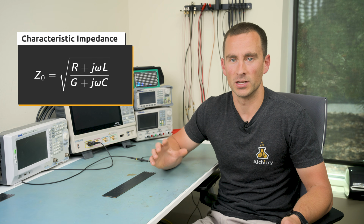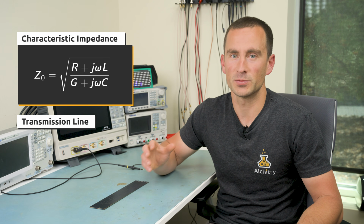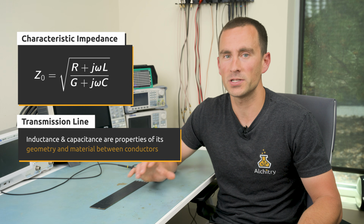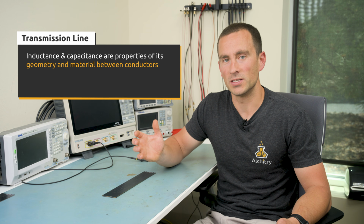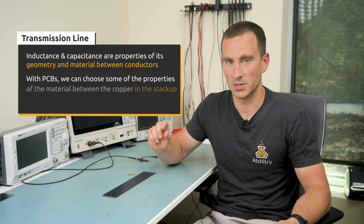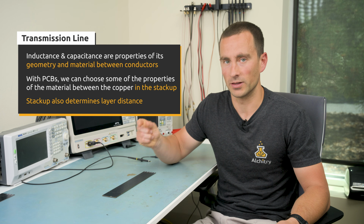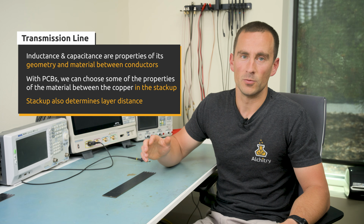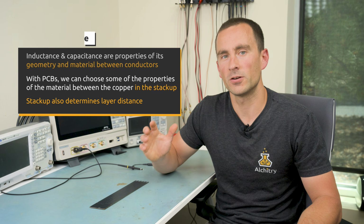The major difference is that the energy in the cable travels down it, but the energy in a resistor dissipates as heat. Looking back at the equation, we can see that the impedance of a wire is mostly determined by its ratio of inductance to its capacitance. A transmission line's inductance and capacitance are properties of its geometry and the material between the conductors. When working with the PCB, we can choose some of the properties of materials between the copper when selecting a stack-up. The stack-up also determines how far apart the layers are. For a given stack-up, we can then figure out how wide our traces need to be to achieve the impedance we want. We'll dive into all that in the next video.